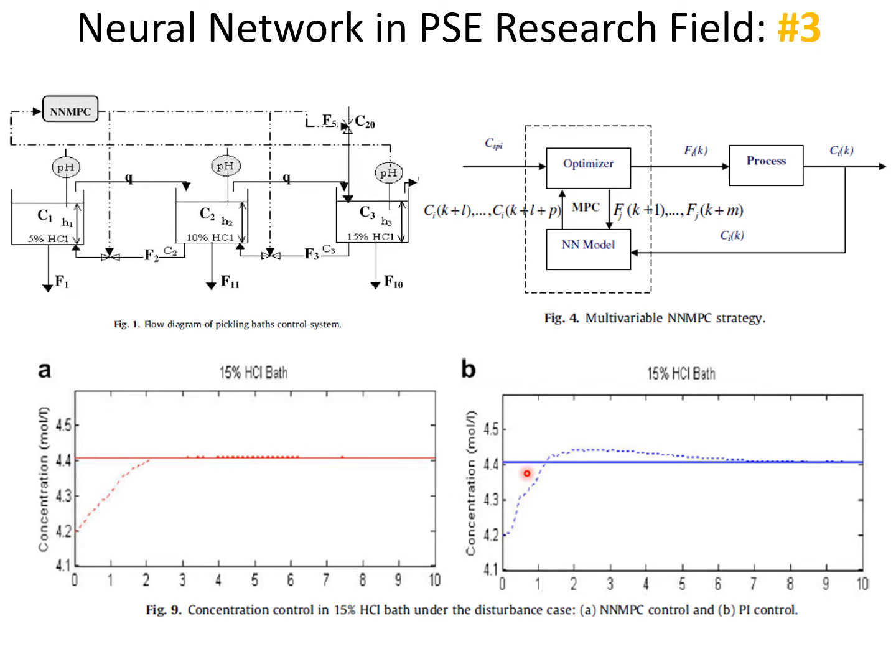It doesn't have too much variation or overshoot, it's very tight to the set point with little variations, and quite often faster to reach the set point, which is much needed in this sort of system, which we want to control quickly and fast, but at the same time tight, without much variation, because that can spoil the whole system if we have too much variation within the concentration. So this is where advanced control is a must for this sort of system, and neural network AI controllers have shown the capabilities in this sort of thing.